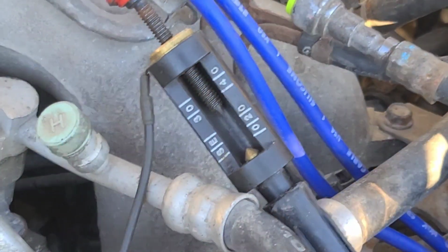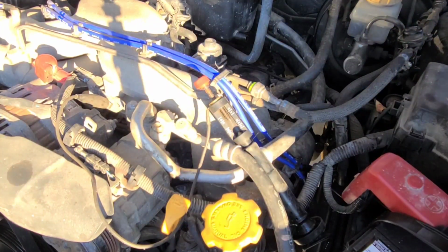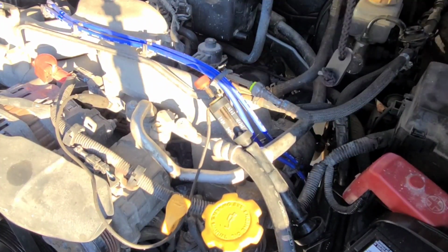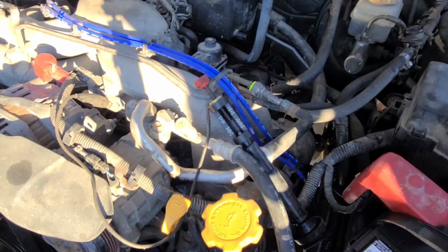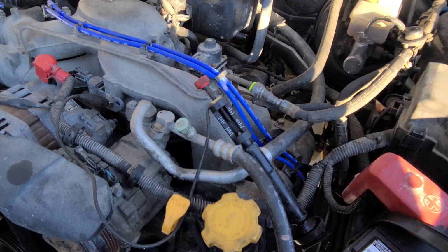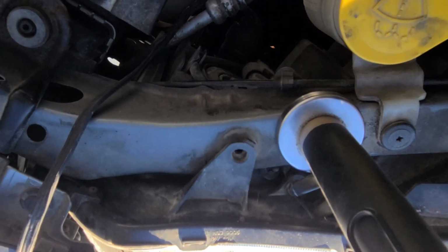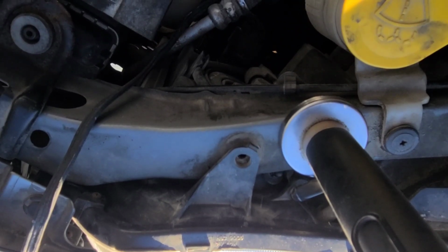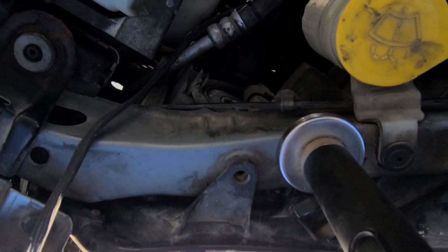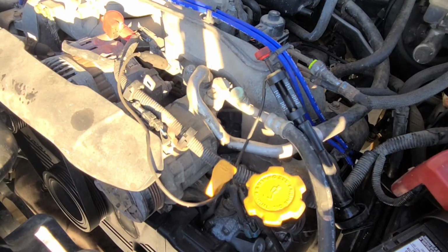I've got to replay this. Well, that's special. It's got no spark, yet we had an RPM signal and injector command. I wonder if it's got an injector pulse though. I'm trying to see if I can get at one of the injectors to put a noid light on it, but they're buried in here. There's a heat shield in the way. And the intake manifold's in the way. Oh my goodness. Well, the injectors are nearly impossible to get to.